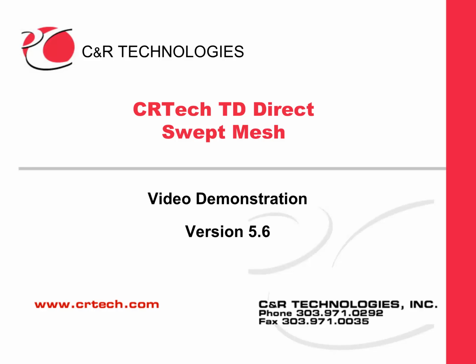Welcome to this video demonstration on swept meshes using TD Direct. A swept mesh is a type of structured mesh where a mesh is extruded from a source to a destination across a region. If the source and destination are edges, then the mesh will be across a surface. If the source and destination are surfaces, then the mesh will be across a solid.